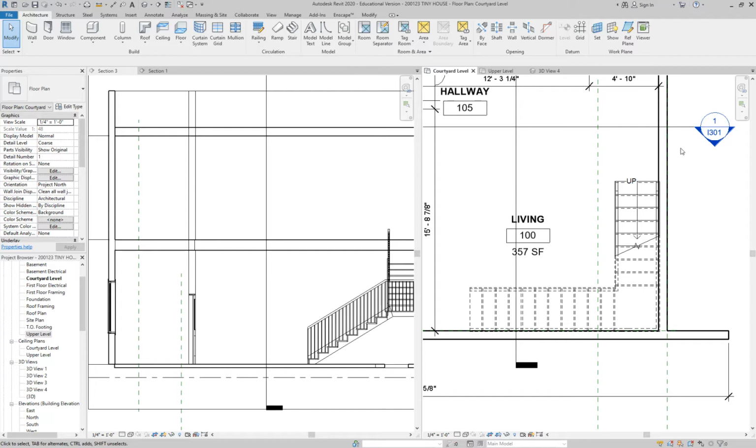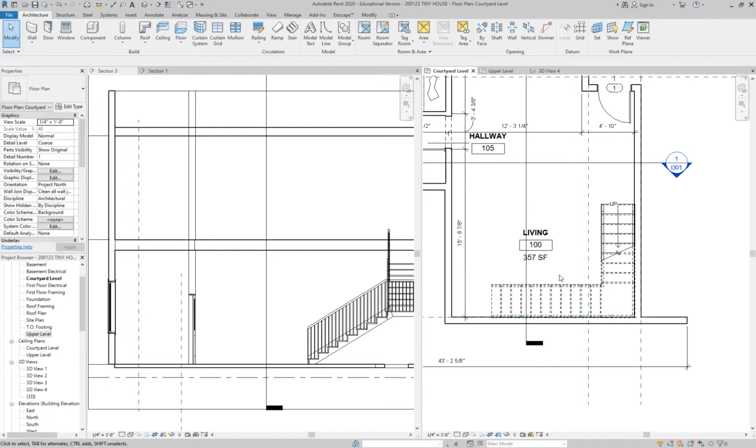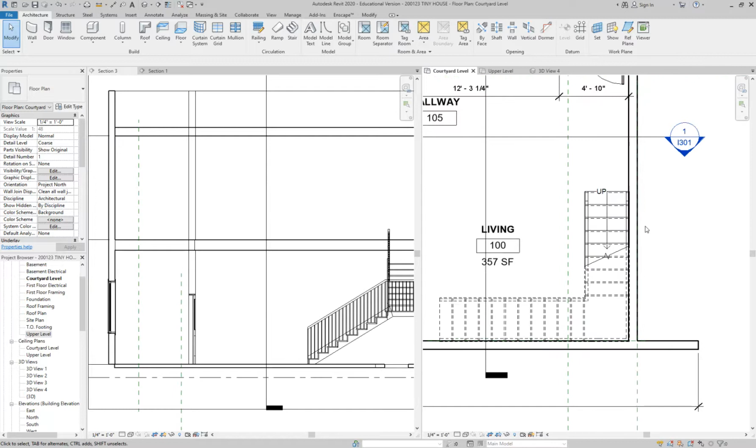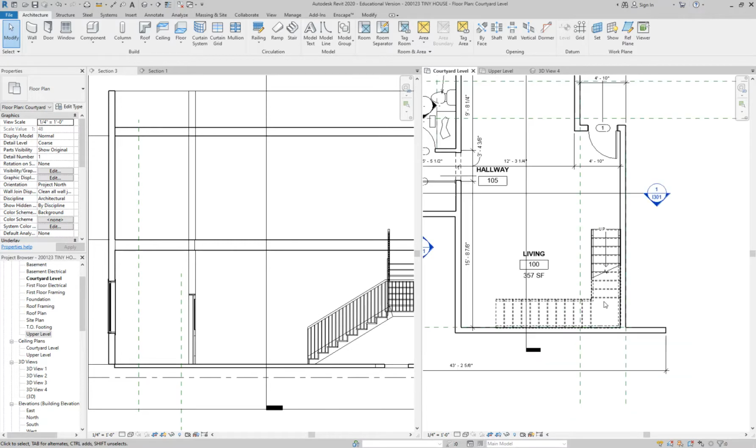Okay, now that we have this, let's start applying some rules to it. And again, this is going to be tricky because we're going at it blind. But the rule that I want to put down is that I want the stair to turn, and I have to completely redraw my L the other way. In a nutshell, I want to make sure that I only have 3 or 4 steps going up, and then I want a 4-foot landing to a turn. Does that make sense? Let me draw it first. Don't even try. Just watch how I would walk through it, and then we'll do it together.